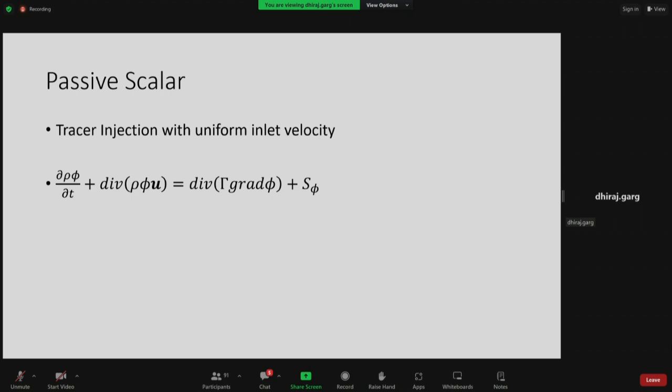When we are taking any tracer, let's assume that the tracer should not be a diffusive tracer. Many of you must have done the very simple experiment of showing the transition from laminar to turbulent using a dye. In that, it's a natural assumption that the dye is neutrally buoyant so that it remains at the same horizontal level where it is injected. And we also assume that it should not be diffusive.